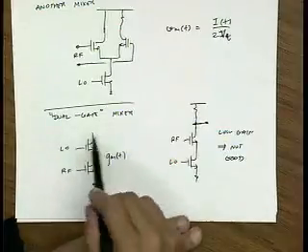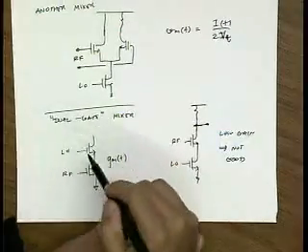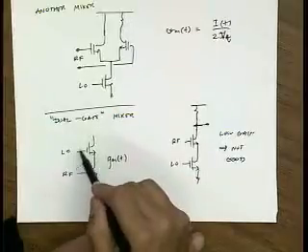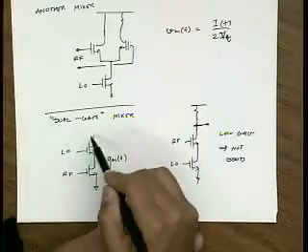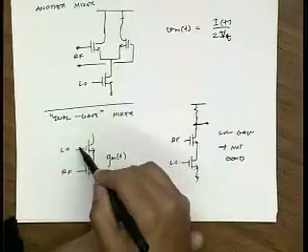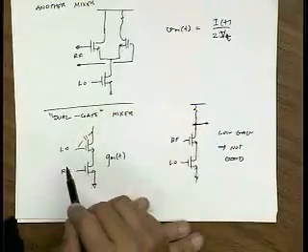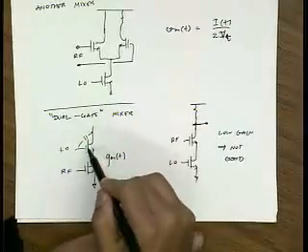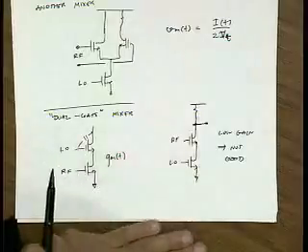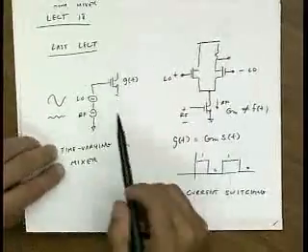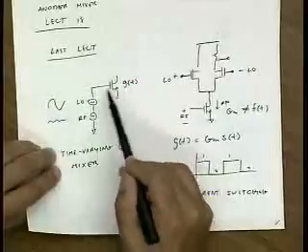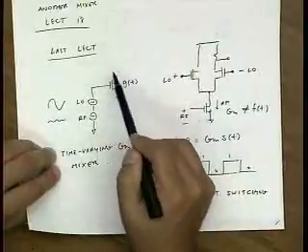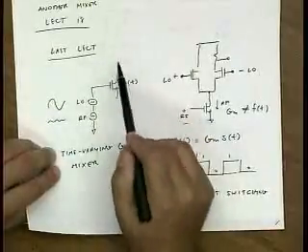Also, to first order, if you look at this mixer here, you can see that because the gain is low for the LO port, there's a natural amount of LO rejection here, right? There is some capacitive feed-through as well, but overall, the LO signal is not amplified to the output like in this circuit. So in this circuit, the LO port sees the full GM of this device to the output, and we rely on the filtering to reduce the LO leakage.